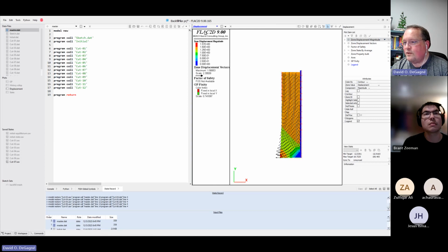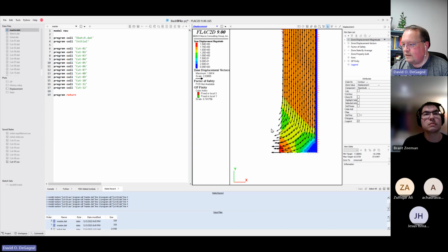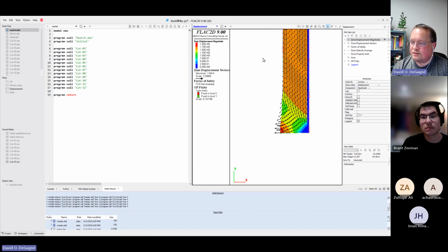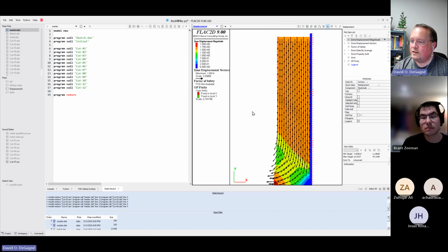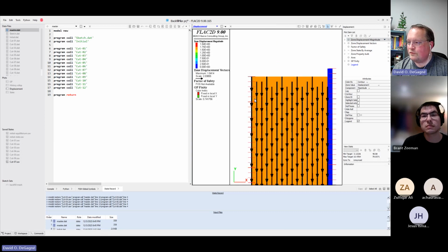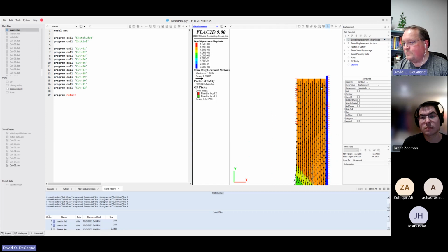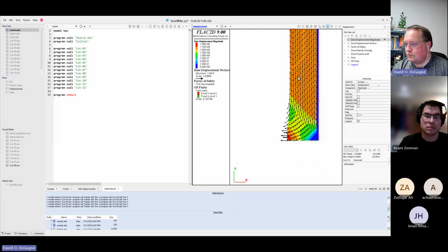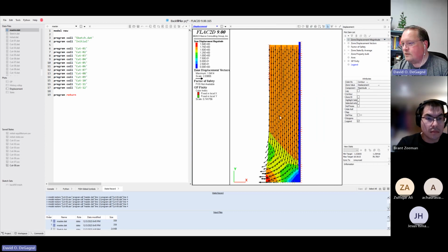And you can see here that we're already getting 1.6, 1.7 meters of displacement, which isn't terribly encouraging because this is 15 meters. So probably the initial template cohesion is not high enough to solve your problem. Also note that this was originally at this height, and so through this process, the backfill is already kind of compacted and displaced that vertical distance, in addition to the displacements that are happening here along the face.